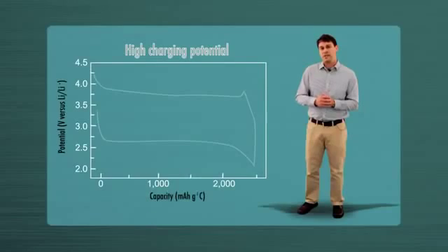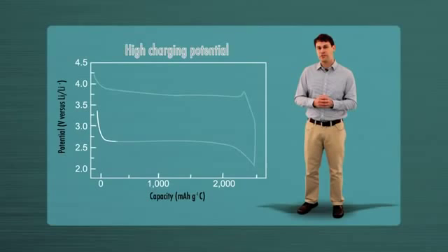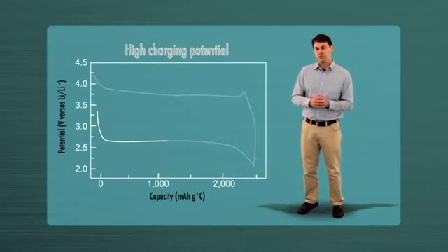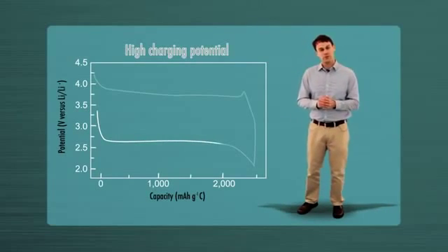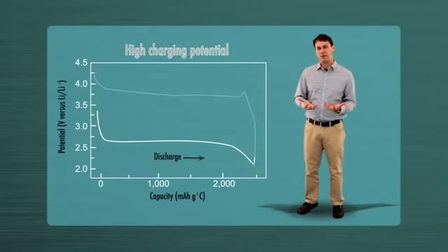Let's talk about some of the other limitations, some of the barriers to realizing these benefits in a real battery of the future. So I've already mentioned the power density issue. You can see on the left, we've plotted the voltage as a function of charge state. And there's two lines here. The bottom curve represents the voltage we get out during discharge of the battery, around 2.7, 2.8 volts.